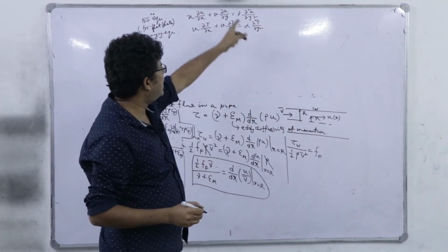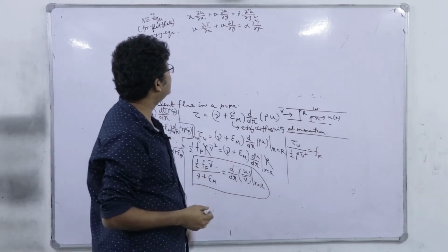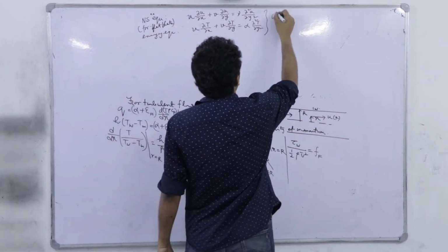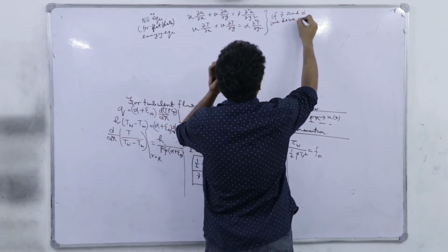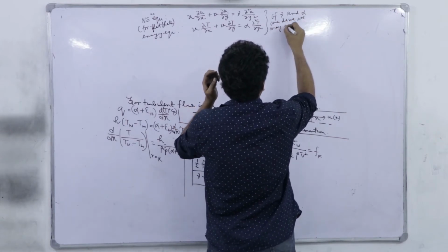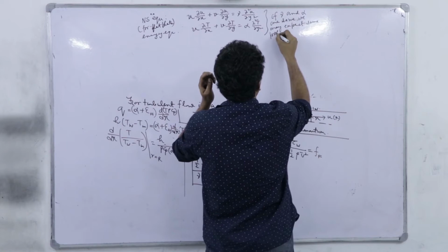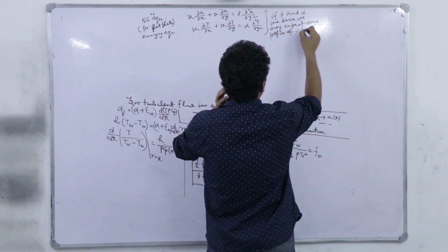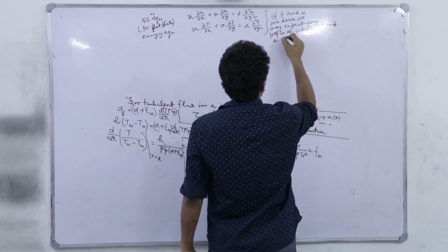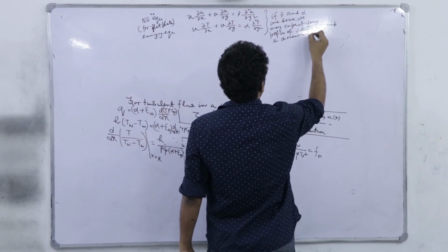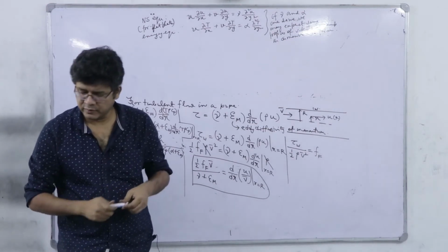So, if I convert this U and V into dimensionless form and T also in dimensionless form, and if nu and alpha are the same, we may expect the same profiles of velocity and temperature in dimensionless form. And that is the basic idea here as proposed by Reynolds.